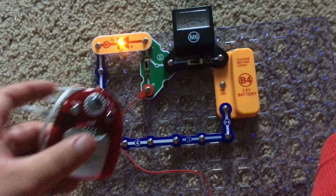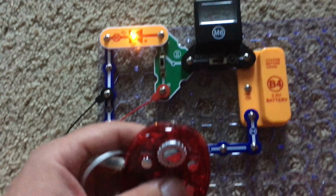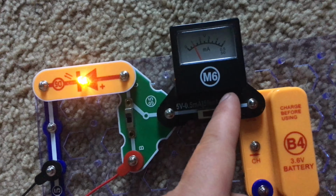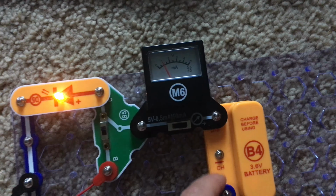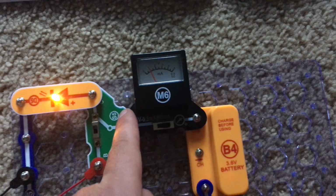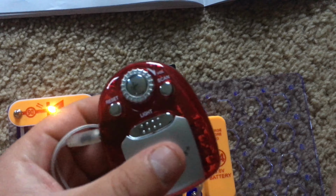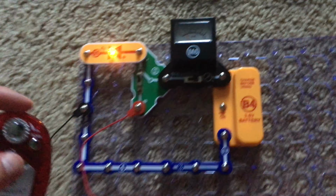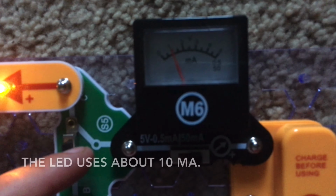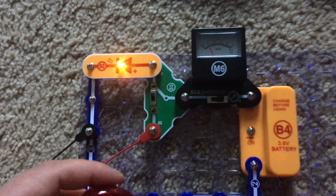Project 115 shows the difference in electrical efficiency between LEDs and incandescent bulbs. You might wonder why I'm using the radio, but that's because it has a built-in incandescent lamp, and the voltage meter, which is set on the 50 milliamp setting, will measure the current from the yellow LED as well as the incandescent lamp on the radio. Now the radio is off, and about 10 milliamps is generated by the yellow LED.